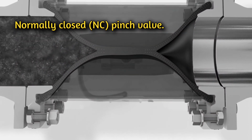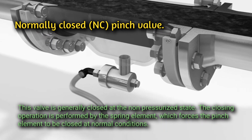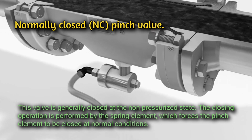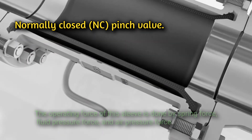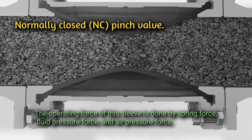Normally closed pinch valve. This valve is generally closed at the non-pressurized state. The closing operation is performed by the spring element, which forces the pinch element to be closed at normal conditions. The operating force of this sleeve is provided by spring force, fluid pressure force and air pressure force.